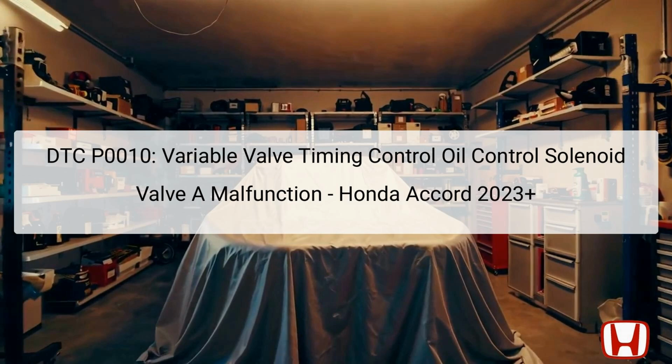The PCM is responsible for monitoring various engine functions and responding to ensure proper performance, which includes managing the oil flow to the variable valve timing system. When a discrepancy is reported, the PCM logs this issue and triggers the check engine light, indicating a need for diagnostics. The VTC oil control solenoid valve is pivotal in regulating the timing of the engine valves, influencing engine performance, economy, and emissions. If this component fails, it can lead to various engine performance issues while driving, emphasizing the importance